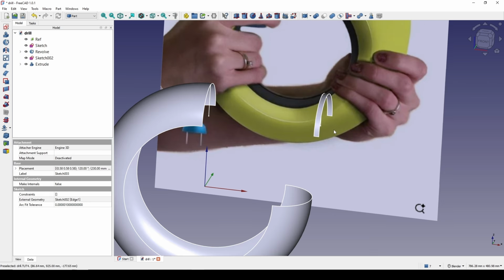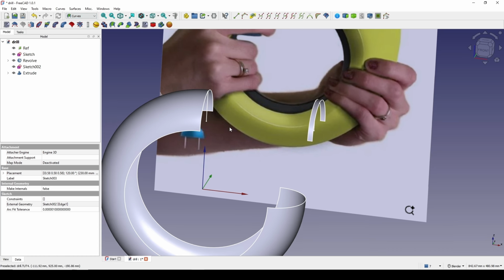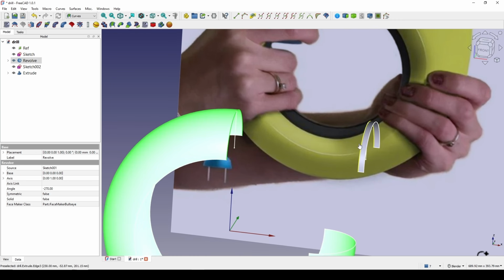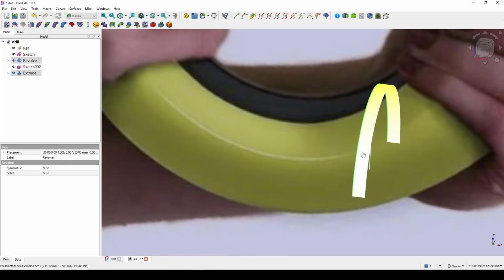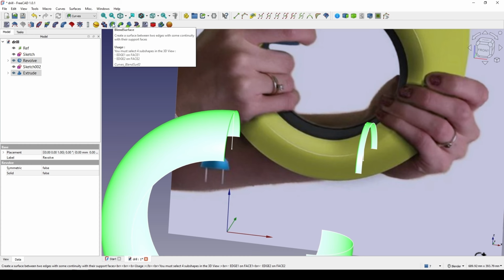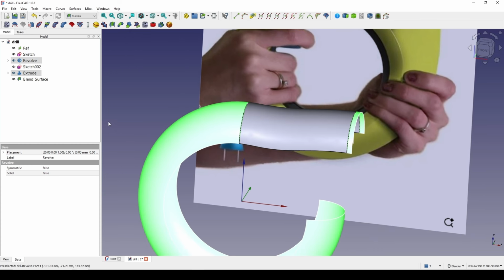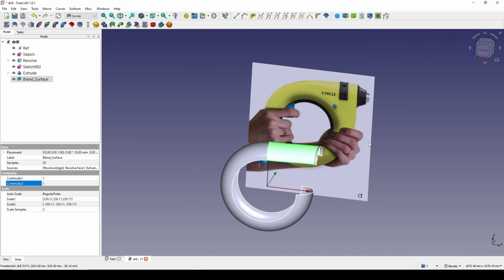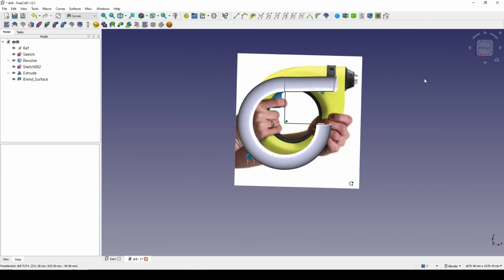Now to use the plane surface, I go to the curve bench, Control select this edge and this face, this edge and this face. Plane surface. And click on the plane surface, go to the G1 continuity for the issue. Okay, now this is the result.